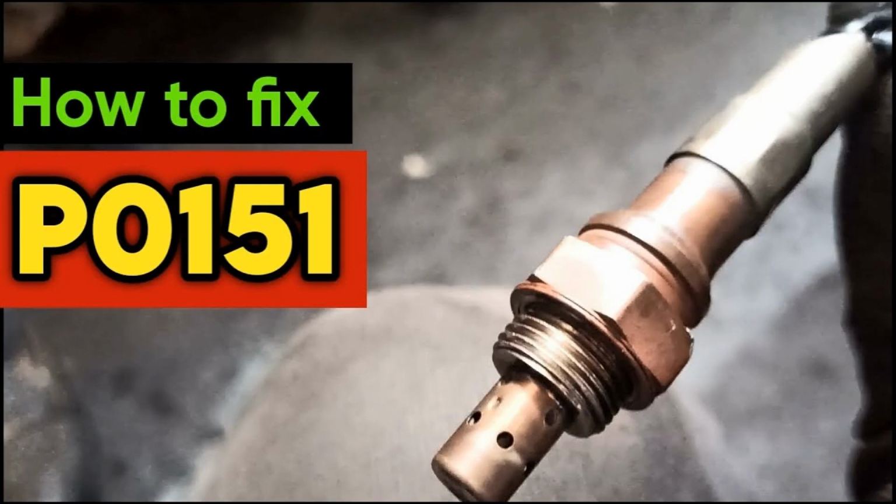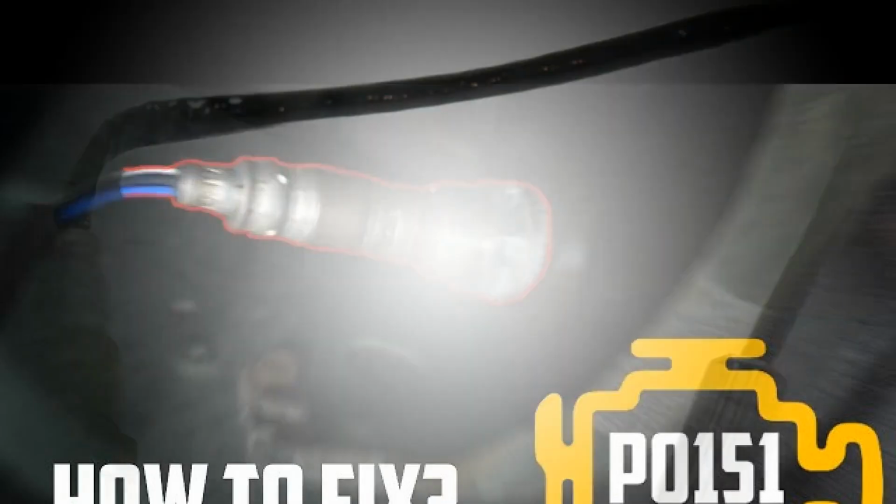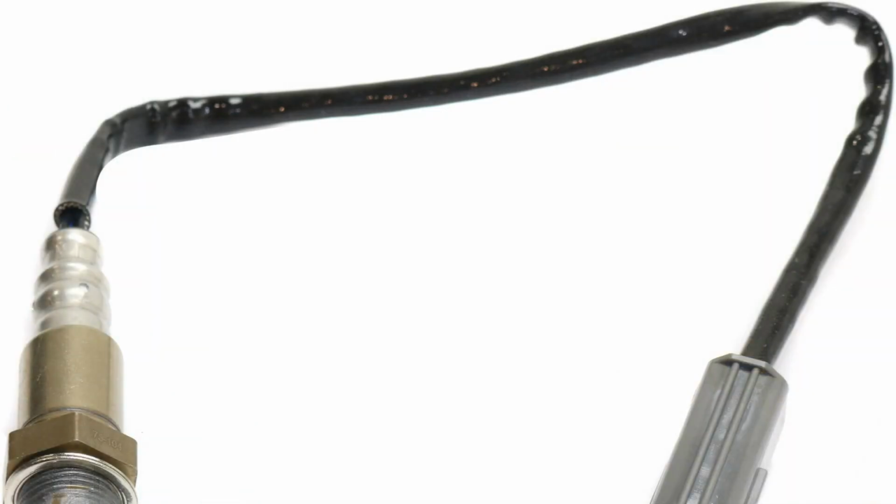Code P0151 is similar to P0136, P0137, and P0131. This code warns of an oxygen sensor fault upstream of bank 2. Bank 2 sensor 1 is located in front of the catalytic converter. It analyzes the amount of oxygen in the exhaust before it enters the catalytic converter. The PCM uses this information to adjust the vehicle's air-fuel ratio. Since the upstream O2 sensor is the main feedback for fuel control, other codes can be stored with P0151 and the engine can therefore remain in open loop.